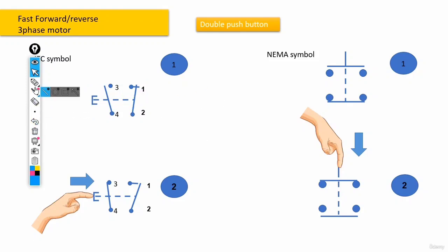Now, as you can see, we have these contacts here. If we don't push the button down, this contact, number 3, would remain open, and the other one, number 1, would remain closed. And again, guys, we have two types of contacts, normal closed and normal open. But if we start pushing the button, contact 3 would be closed, and contact 1 obviously would be opened.